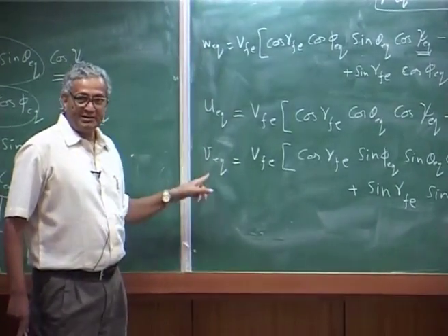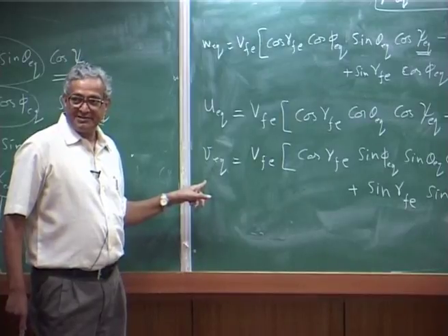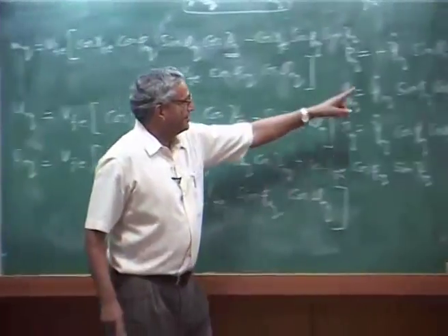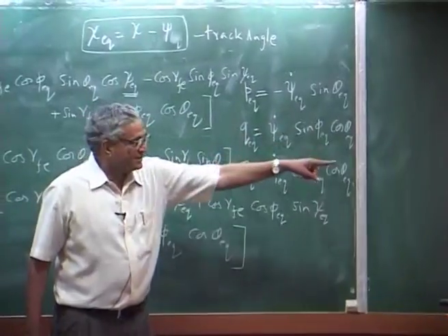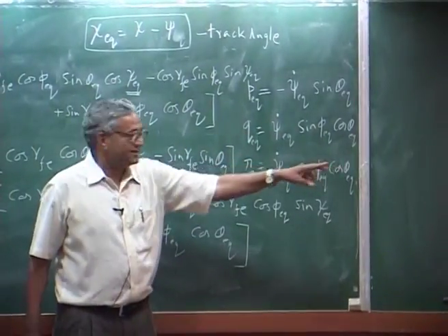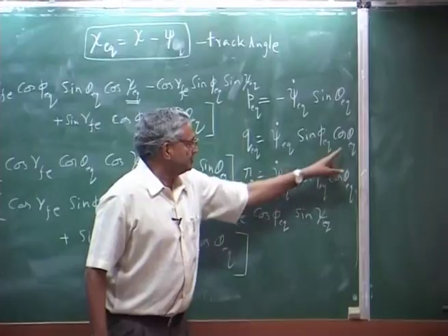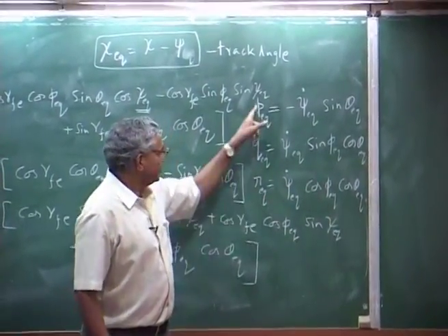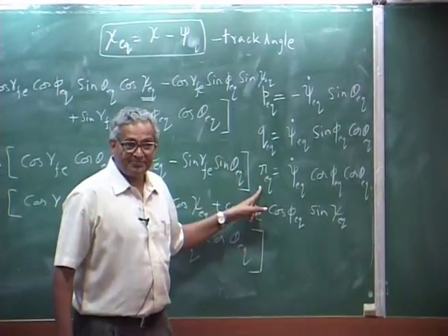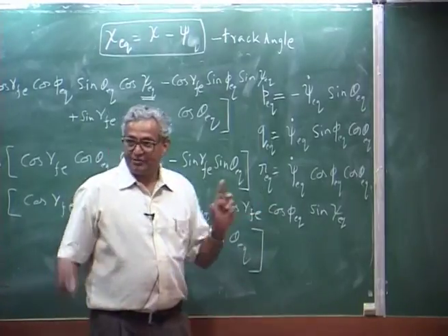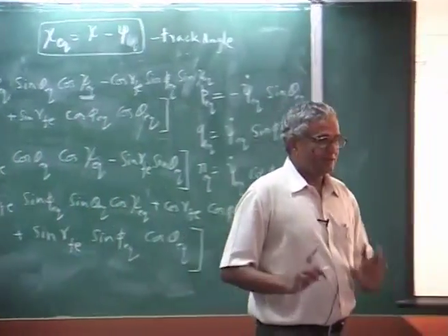That means, you have all the 3 quantities, okay, and given psi dot, that is the input equilibrium turn rate. You have already assumed theta EQ, PEQ. That means, I know PE, QE, RE. Okay. You go back to the 6 equations and then solve. I will just briefly mention, because this procedure is quite complicated, that is where the convergence comes in. See, here I briefly describe the procedure that is done.